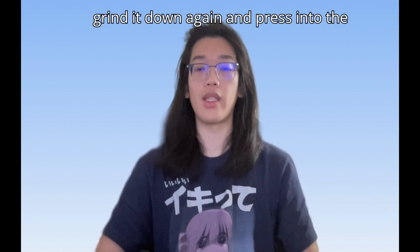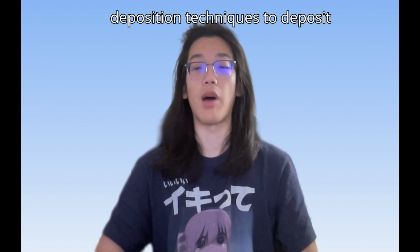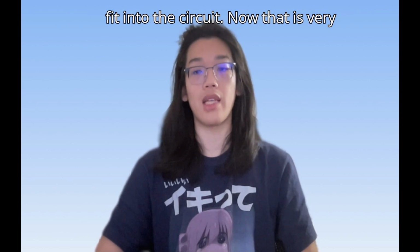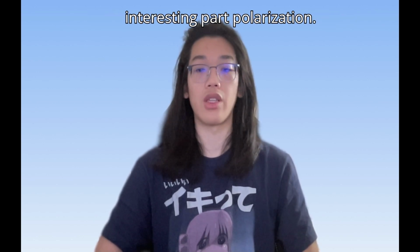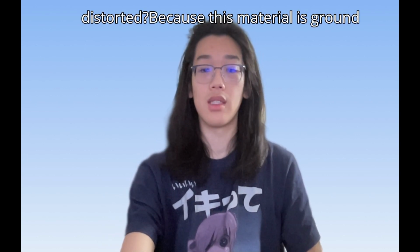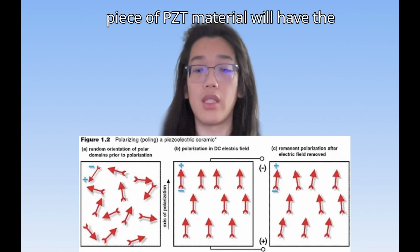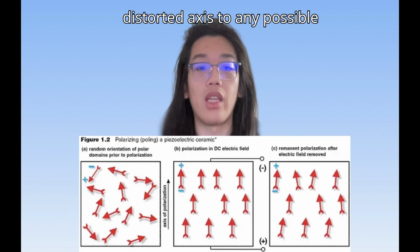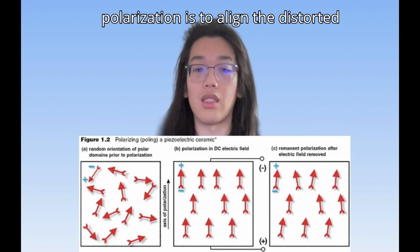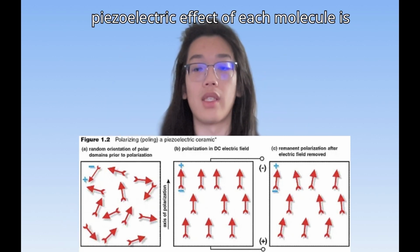The next step is to grind it down again and press it into the desired shape. Use physical vapor deposition techniques to deposit microelectrodes on it to make it able to fit into the circuit. Now comes the very interesting part, polarization. Remember the small unit cells that are distorted? Because this material is ground to powder and reshaped, the unpolarized piece of PZT material will have the distorted axis in any possible direction. Thus, the purpose of the polarization is to align the distorted axis to the same one, so that the piezoelectric effect of each molecule is added up.